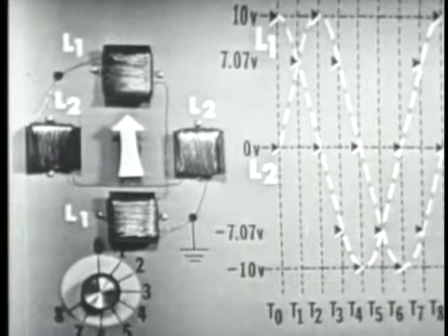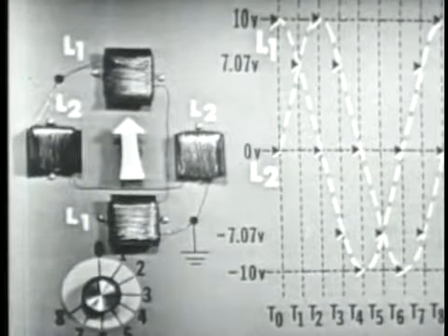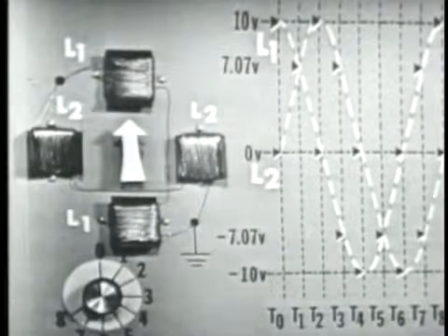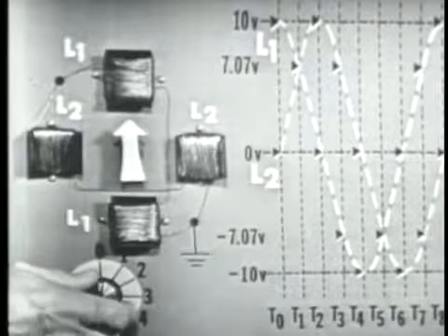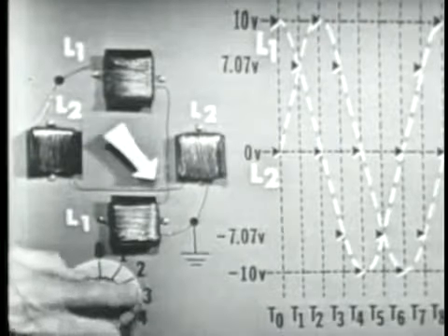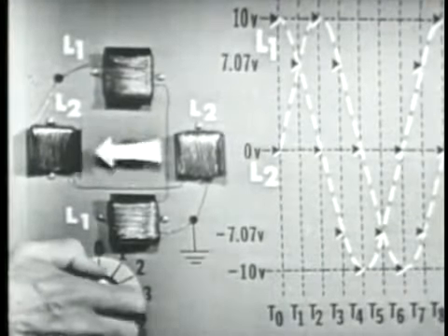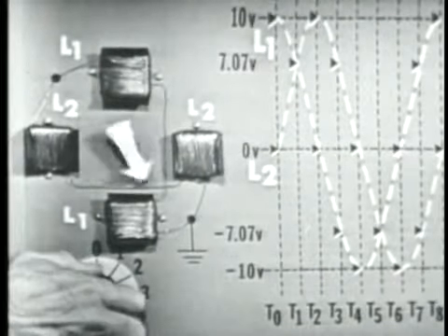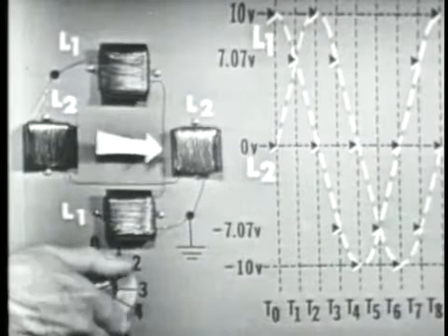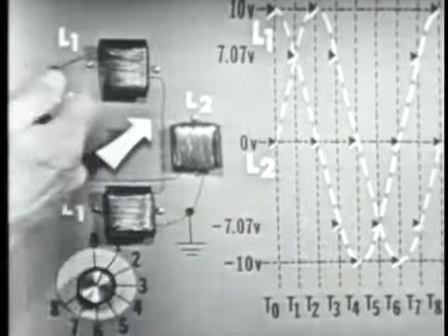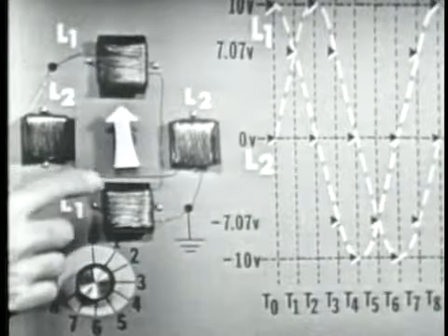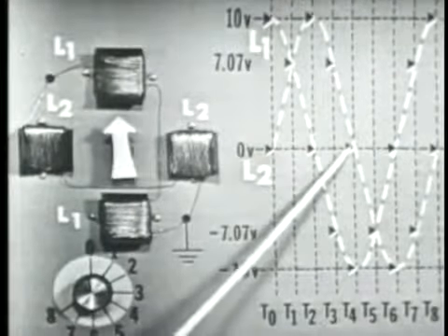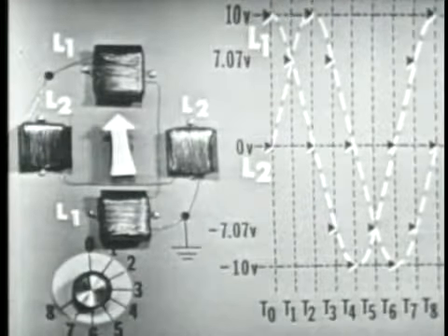Okay. A rotating magnetic field is achieved by applying out-of-phase voltages to the stator or the field windings, which we represented on this demonstrator. Now, you should point out, Bob, that the most effective phase difference to use is 90 degrees, as we did. Right. It'll work at other phase differences. In fact, any phase difference other than 0 or 180 will give you a rotating magnetic field. But as you said, the most efficient one is 90 degrees phase difference, and that's probably most commonly used.